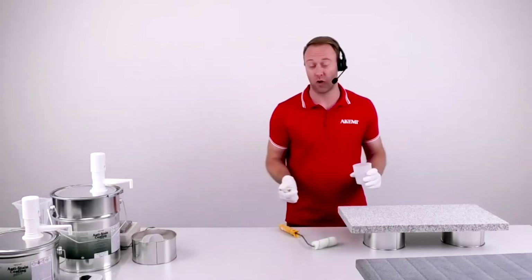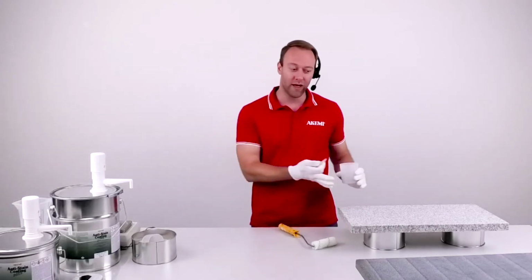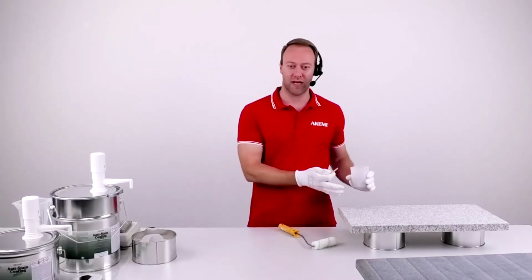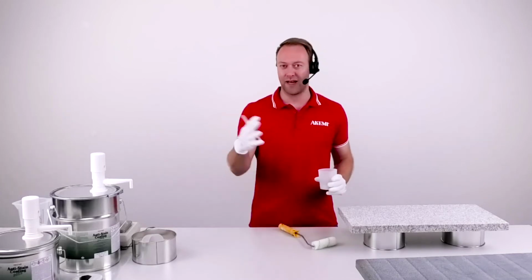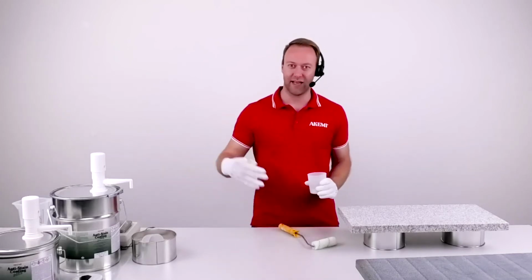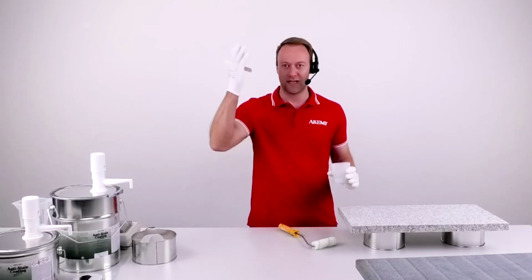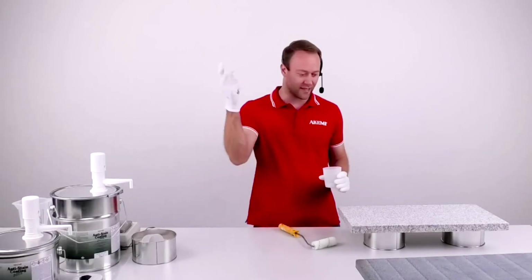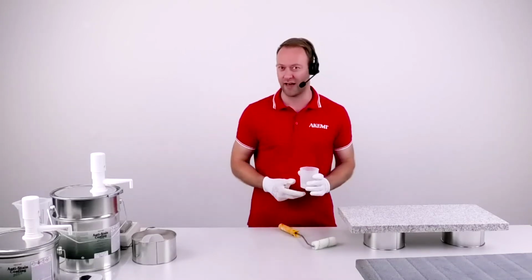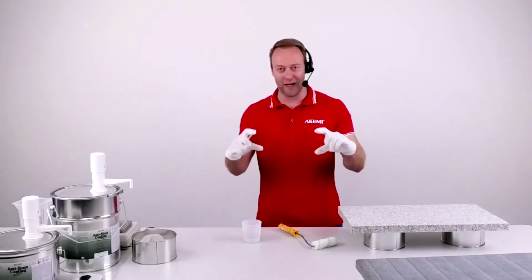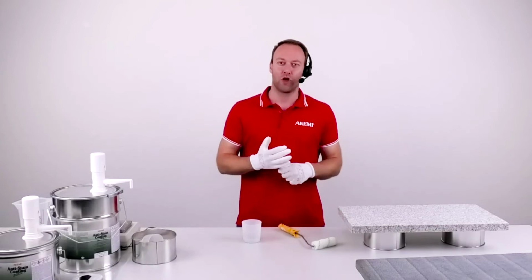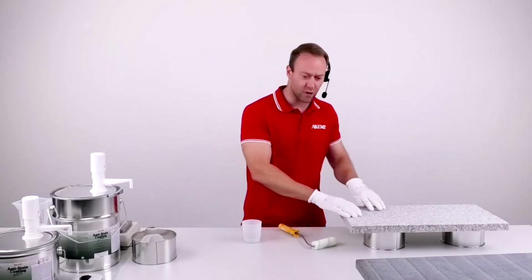I've seen also in the summertime people doing it in the morning on the construction site, doing the tiles. After lunchtime, 5-6 hours later, they were installing it, because in summertime at 30-35 degrees, the sun is shining, it cures quite fast. But from the book, at 20 degrees, the curing time is 6 to 8 hours, and it's not sticky anymore.